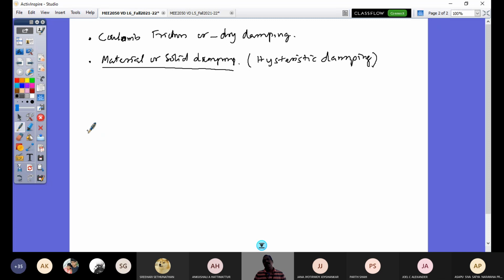In such kind of thing, the damping present would be what is called solid damping or hysteresis damping, where this damping also can be intuitively assumed to be damping with the viscosity. So hyperelastic material definitions and so on for rubber material vibration is concerned. So that all go into tire side when you have to account damping. So that's what you can witness when you are touching the tire of your vehicle at the hot sun. That would be with the higher temperature. When tire is interacting with the road and goes, there is vibration, there is an energy dissipation continuously that is coming out of your tire.